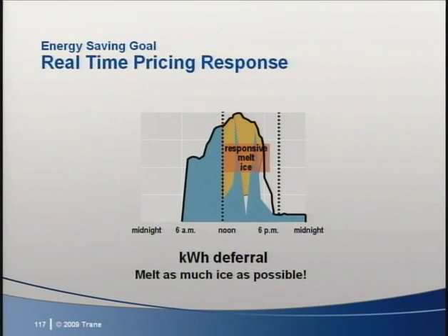It could, however, involve a sophisticated, internet-based real-time utility rate monitoring application. Real-time pricing could really make an ice energy storage system dance. By this, I mean it will want to control the system to be real-time price responsive. With real-time pricing, the electrical utility can change the price they charge for electricity as often as every 15 minutes. The good news is that they give the building a 15-minute warning of a pending change in price. Based on that warning signal, the control system can easily change from an all-chiller cooling mode to an all-ice cooling mode, or even to a combined cooling and ice-making mode. A very nice feature of an internal melt energy storage system is that it is easy to seamlessly change operating modes to respond to such a signal.